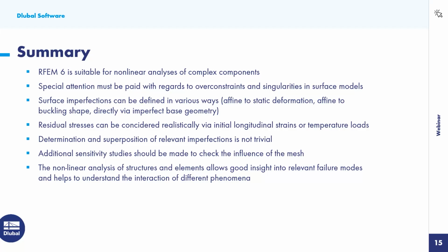But I also want to highlight, and this is my personal opinion, that doing such a type of analysis from time to time, maybe if time allows it in a certain project, you get a much better feeling of the behavior of your elements and your structure if you also activate these non-linearities and push your model over the linear boundaries and see the failure modes and spend a bit of time analyzing the results. You get a much better feeling and engineering judgment for your future work. So I think this still has a place somewhere in our daily routine, maybe.